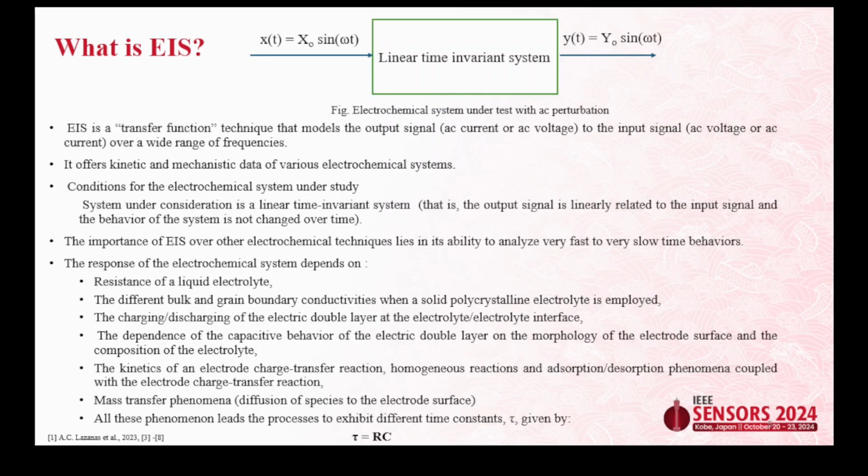So that is why the major aim of getting into an EIS technique is, whatever data we are getting in terms of Nyquist plot or Bode plot, we have to convert that data in the form of an equivalent circuit, which we know as Randles' equivalent circuit, so that we can analyze that circuit in terms of resistance and capacitance, and we can compare the data for all the applications based upon these passive elements only.